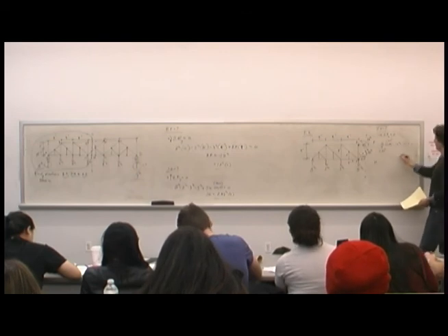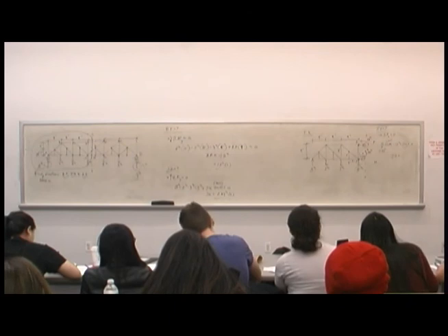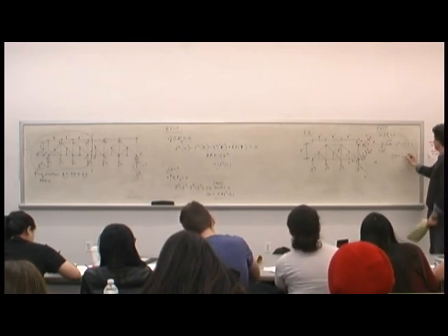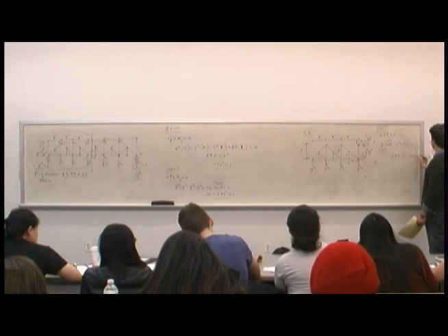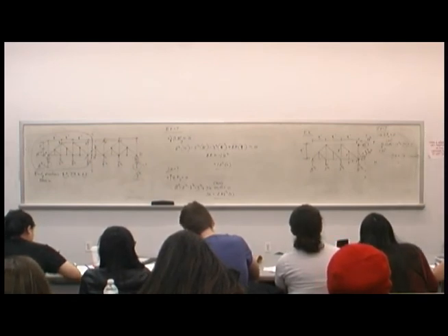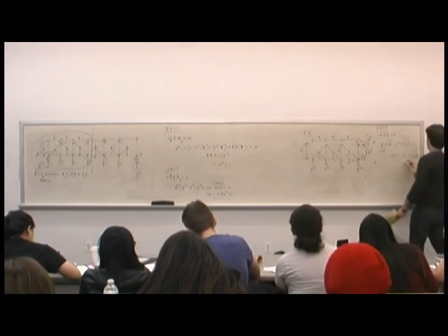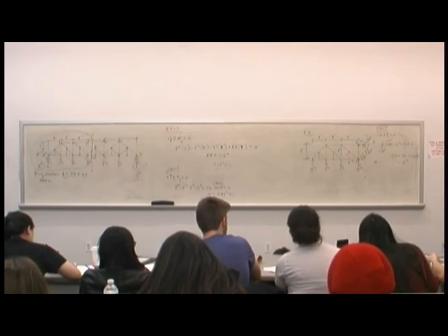So solve for JH. JH becomes 17 minus 2.83 times 0.707. Yeah, 15. And is that tension, compression? It's pulling away from the node? Tension.